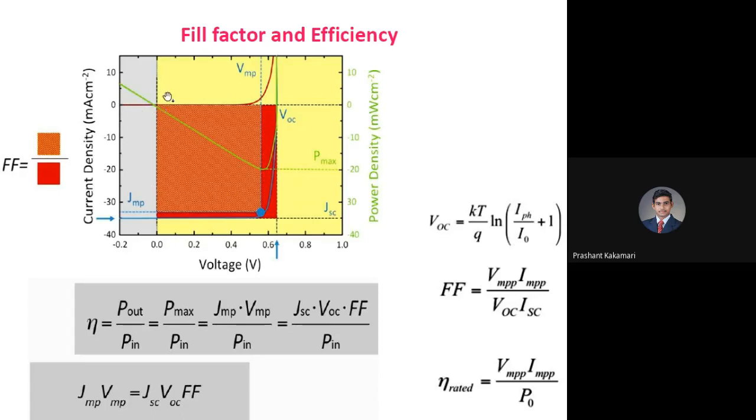Once it starts illuminating, what will happen? The electron flow will increase, because of which the voltage is going to increase in this direction, and the current is also going to increase in this direction. Just see the values; don't look at the negative or positive sign. In these values, you can see the current goes on increasing as you increase the solar illumination or radiation. Due to this, current density and voltage are improved, and one can now define the fill factor and the efficiency for this curve also.